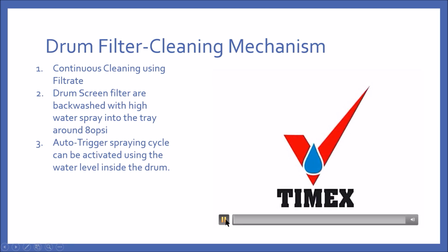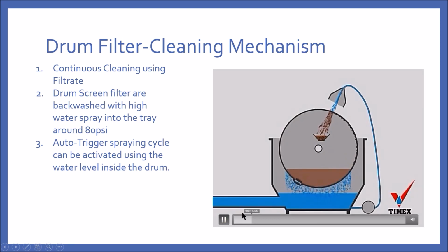Water will enter the drum filter in the middle, as explained earlier. As the drum rotates, it builds up what we call a filter cake. This filter cake will accumulate on the side of the wall, while clean water will pass through the drum and be filtered. Firstly, it is important to control the pore size of the drum, as different pore sizes will give you different filtering capabilities as well as different flux.